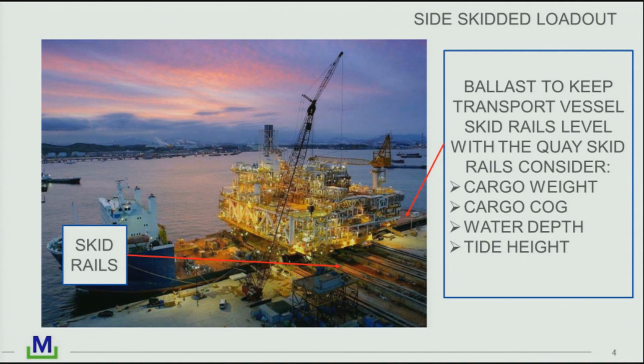These vessels have multiple ballast tanks. Some of them have over 60 individual ballast tanks. The typical type of damage case that we look at here is we sometimes get corrosion in the bulkheads and we pump ballast into one tank and the ballast goes somewhere else. And that makes a loadout very difficult.